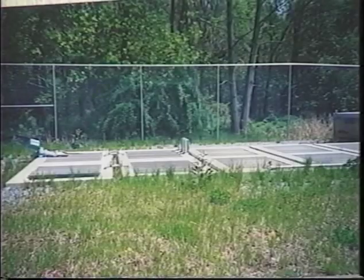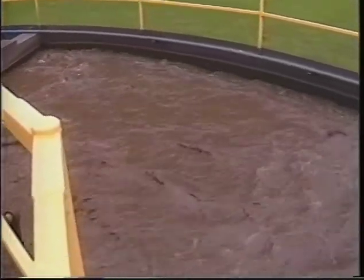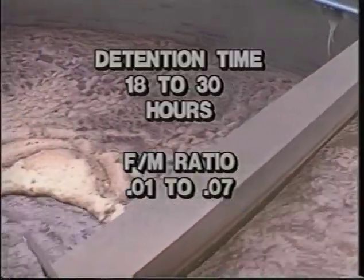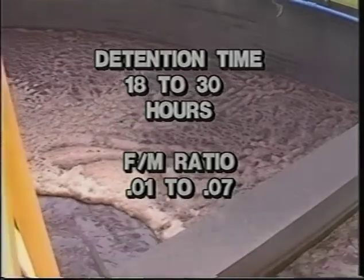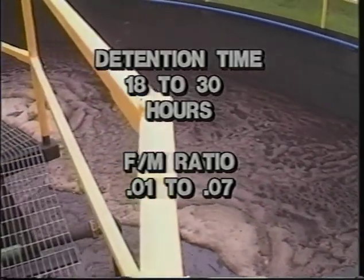The extended aeration-activated sludge process is most commonly associated with package plants. The configuration of the extended aeration system is similar to the conventional activated sludge plant, except the detention time in the aeration tank is 18 to 30 hours with an F to M ratio of 0.01 to 0.07.